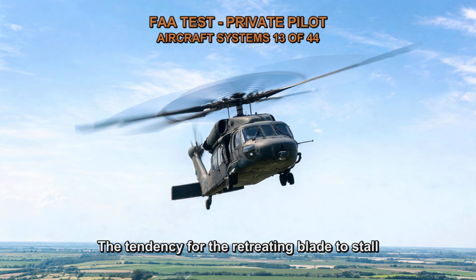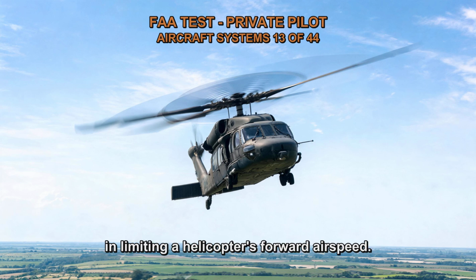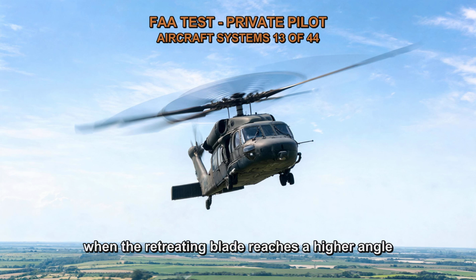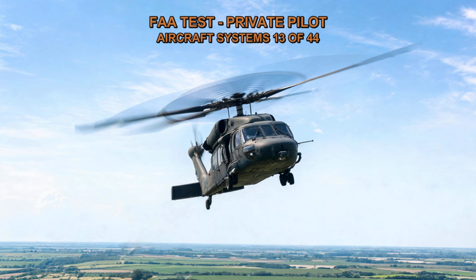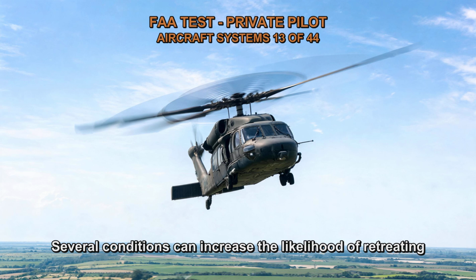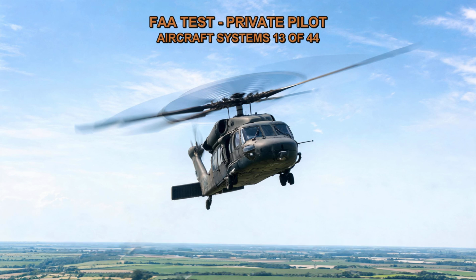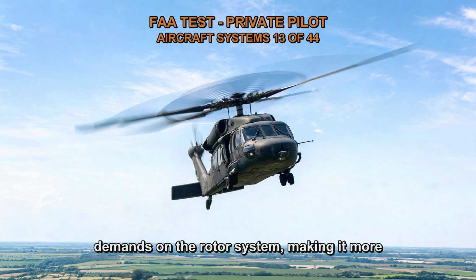The tendency for the retreating blade to stall in forward flight is indeed a significant factor in limiting a helicopter's forward airspeed. This phenomenon, known as retreating blade stall, occurs when the retreating blade reaches a higher angle of attack and experiences reduced lift compared to the advancing blade. Several conditions can increase the likelihood of retreating blade stall, especially when operating at high airspeeds. These conditions include 1. High gross weight. A heavier helicopter places greater demands on the rotor system, making it more susceptible to stall at higher speeds.